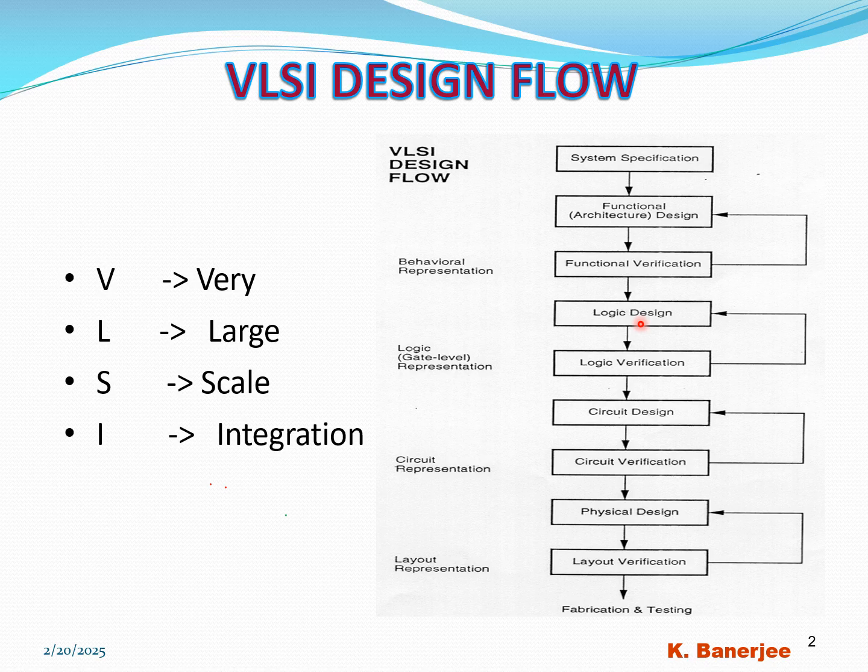The next stage is circuit design. Basically, circuit design is switch level design, and another name for the circuit is netlist. So this netlist design is at the switch level, and the circuit verification is mainly done by SPICE, you know.